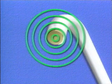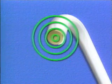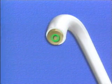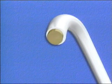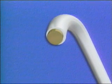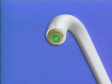After the current flowing through the conductor reaches its peak positive value, it decreases until it reaches zero. As current flow decreases, the magnetic field collapses. The motion of the magnetic field collapsing is opposite to the motion of the field building up. Since the motion is opposite, the self-induction is also opposite. The voltage that's induced in the conductor now has the same polarity as the applied voltage. When the magnetic field has collapsed completely, there is no motion, so there is no self-induction. Then, as current flow starts to increase toward its peak negative value, the magnetic field builds up again.